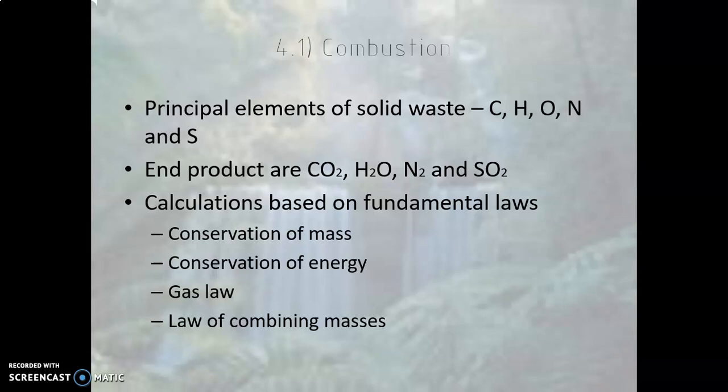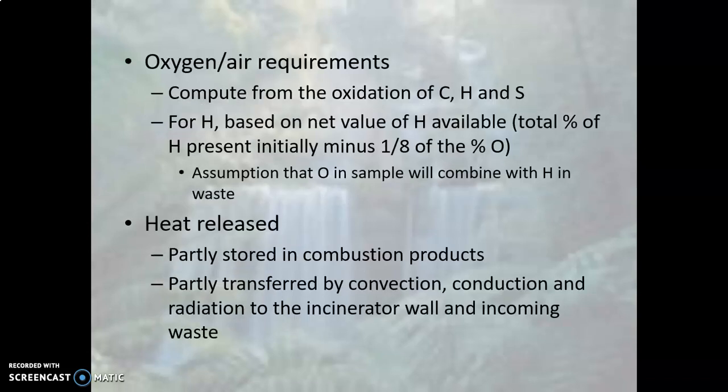Most of the elements in solid waste are C (carbon), hydrogen, oxygen, nitrogen, and sulfur. From combustion, the end products are CO2, H2O, N2, and SO2. During the combustion process, calculation is based on fundamental laws, which involve conservation of mass, conservation of energy, the gas law, and the law of combining masses. In order for combustion to occur, we need the air requirement or the oxygen requirement,